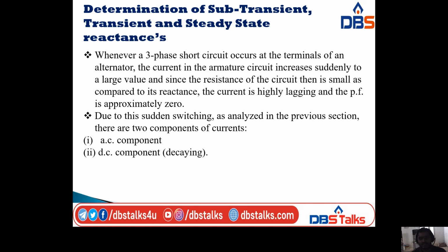It increases suddenly to a large value, and the resistance of the circuit is small compared to its reactance. Since the resistance is small compared to the reactance of the circuit, the current is highly lagging and the power factor is approximately 0.